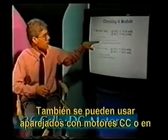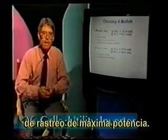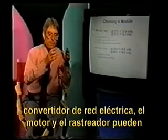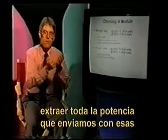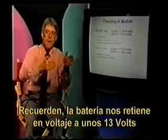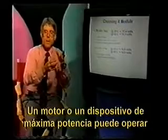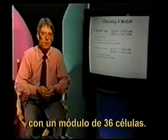These can also be used when they're directly coupled to DC motors or when they're used in utility interconnected systems with max power tracking devices. Why? Because when we're connected up to a DC motor or to a max power tracking device in a utility inverter, the motor and the max power tracker can extract all the power that we deliver with those 36 cells. A battery cannot. Remember, a battery holds us back in voltage to around 13 or so volts, and the max power voltage might be around 15. A motor or max power tracking device can operate at around 15 volts and use all that power. So that's a good match with a 36-cell module.